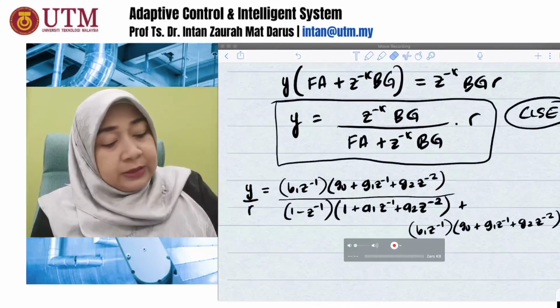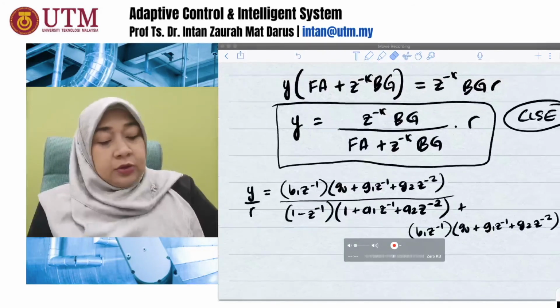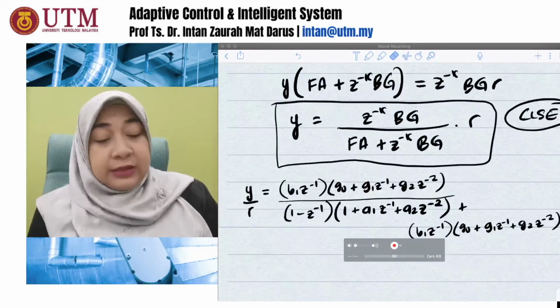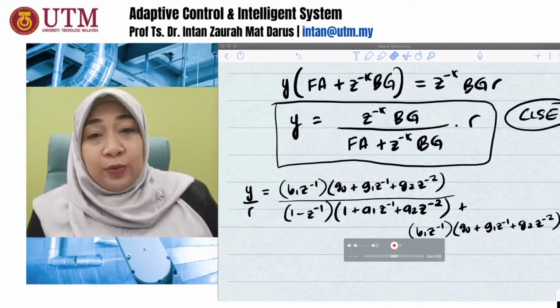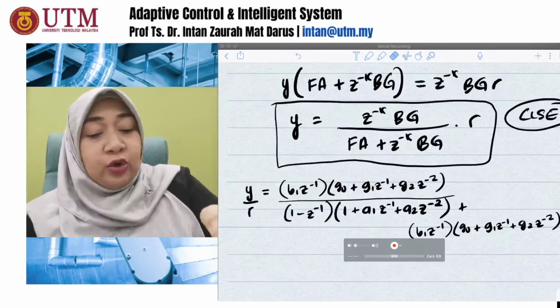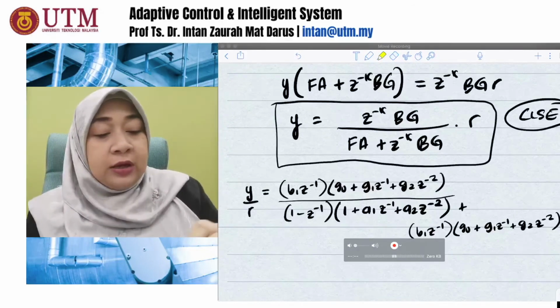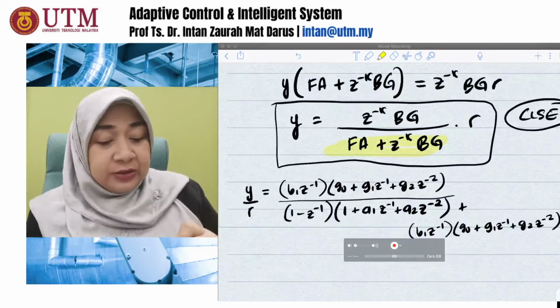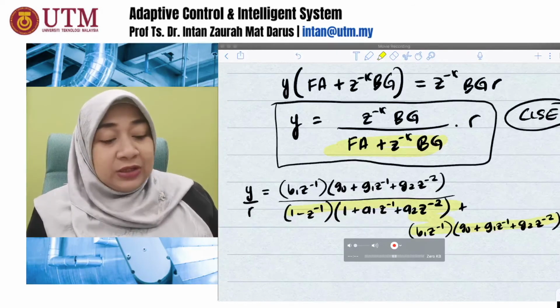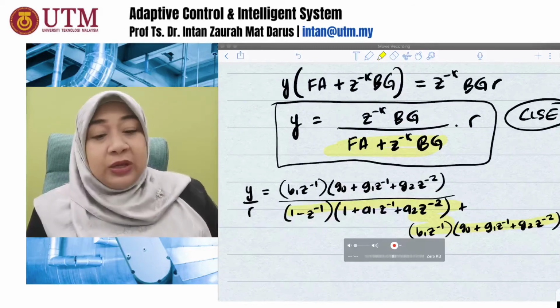Okay, so plus that, so that's going to be your very long denominator that you have for your system. Okay, so that denominator needs to be equated with your stable poles, because your denominator here is your characteristic equation. So these are your characteristic equation. Okay, so you need to actually equate that with your stable poles.